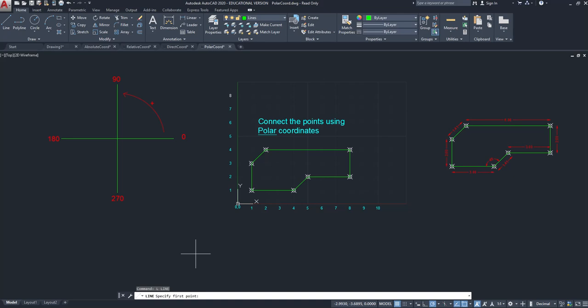In AutoCAD, if you start typing in a command and you think like polar coordinates and you hit a space, the space will act as a return, as an enter, okay? And it will execute the command. So if I type L space bar, that's the same as typing L enter, which executes the command, okay? So L enter to initiate the command, or L space bar.